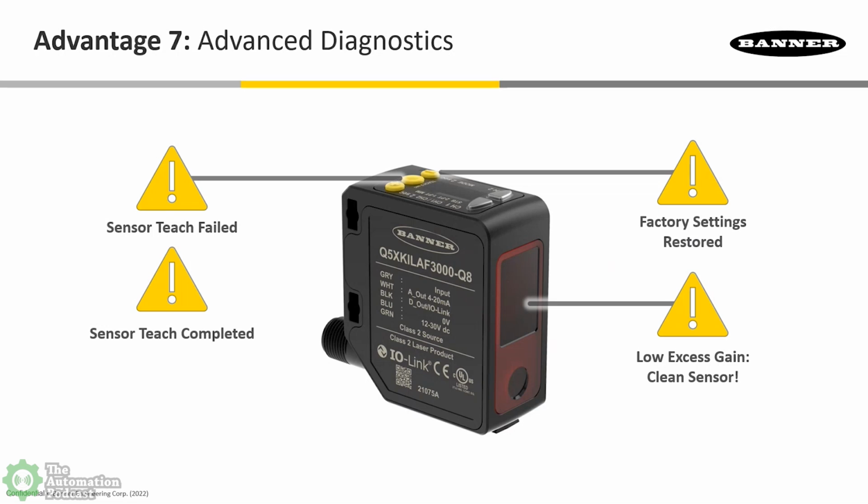And predictive error detection on the device itself is possible because that process data I was talking to you about before is continuously and consistently being sent to the controller automatically. So it makes things like making sure your sensors are healthy a lot easier than it ever was before. Before, it would fail and you would have no indication of it failing before it happens. Now you could actually take corrective action before it fails entirely.